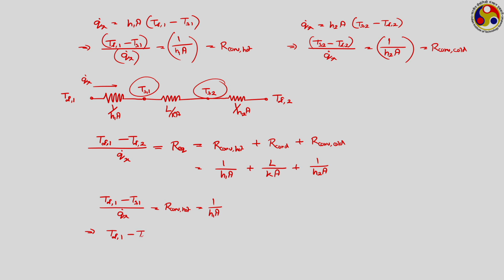T∞1 − Ts1 is equal to Q̇x/(h1 A), or Ts1 is equal to T∞1 − Q̇x/(h1 A).